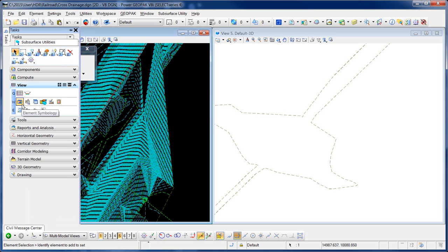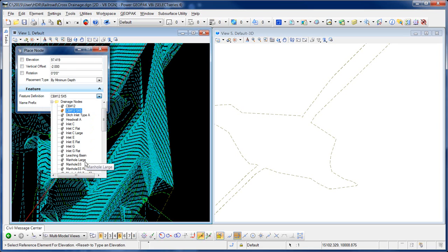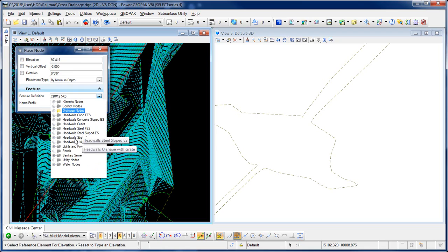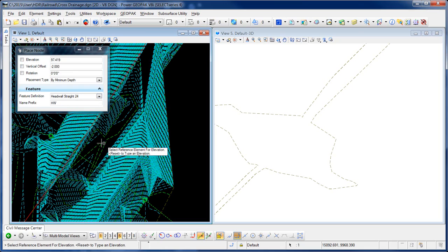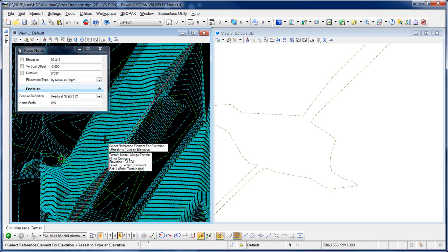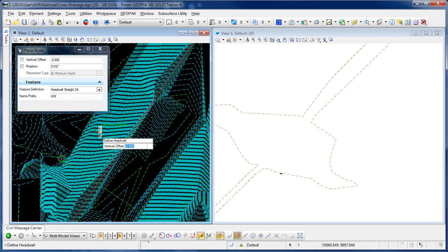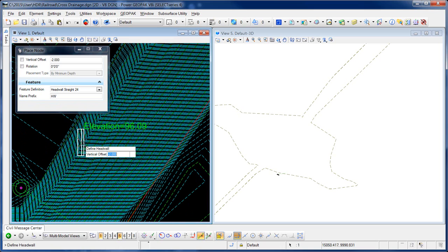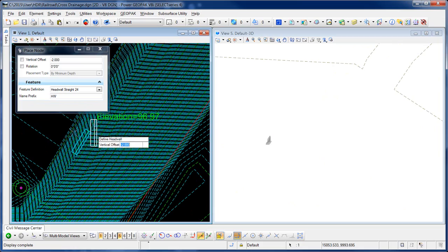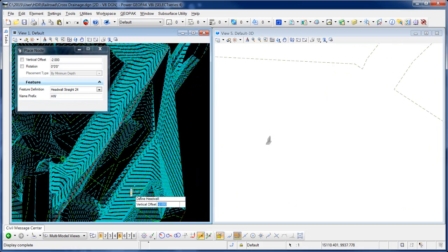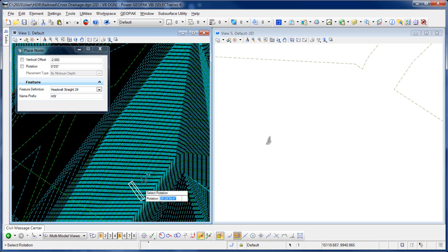And so let's start by building our cross drain, and I'm just going to place two head walls. And I'm going to do something really simple here, honestly, with straight head walls. And so I'll just do something like that. And I'm going to use a 2-foot offset from the ground because for this particular type of head wall, a 2-foot offset gets you pretty well underground without much risk of exposing the pipe. And then I'll put another one over here, let's say.